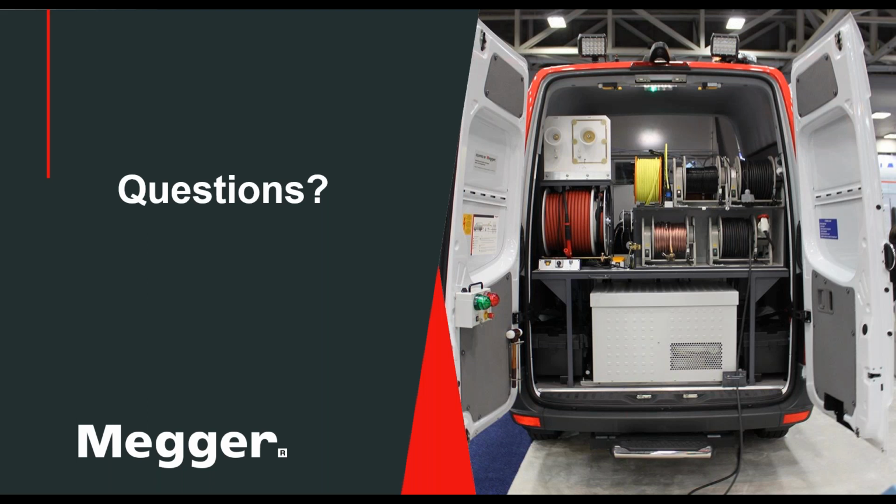During testing, must both cable ends be connected to the equipment or not? Say, for example, a transformer is connected to a motor through the cable. Well, whenever you test, you can only test from one end of the cable. When you do fault locating or cable testing, you have one end connected to your test equipment, and the other end of the cable must be open, must be isolated. It cannot be connected.